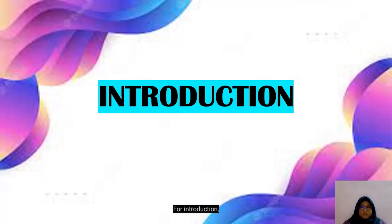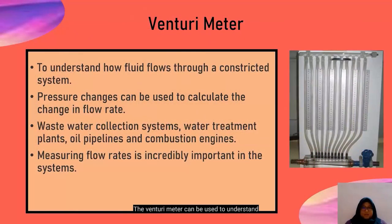For introduction, Venturi meter. The Venturi meter can be used to understand how fluid flows through a constricted system. In constricted system, pressure change can be used to calculate the change in flow rate. Venturi meters are frequently used in wastewater collection systems, water treatment plants, oil pipelines, and combustion engines. Measuring flow rate is incredibly important in systems where a precise mixture is required.